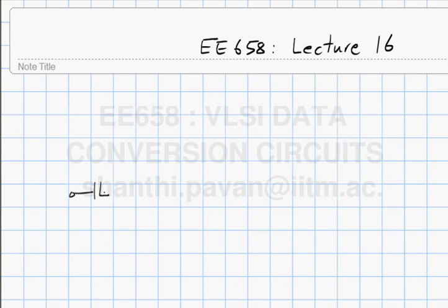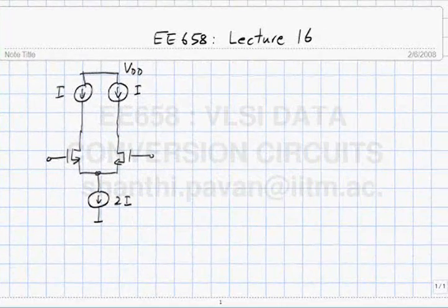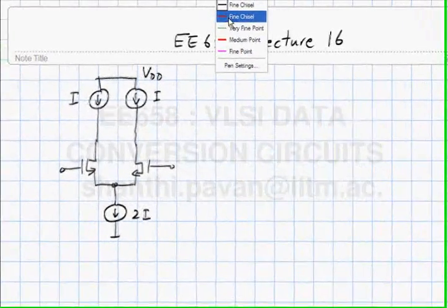making a fully differential operational amplifier was this guy here. And as we discussed yesterday, in order to get a large incremental gain, what you want to do is to use current sources as loads. So the incremental gain you get will be gm times the output impedance of the NMOS transistor in parallel with the output impedance of the current source.